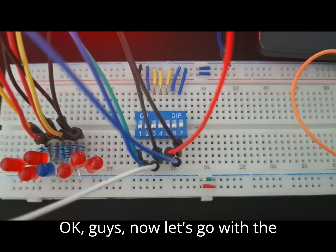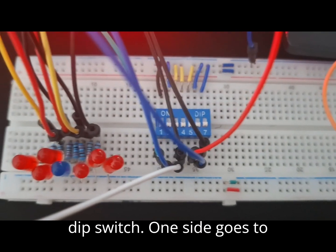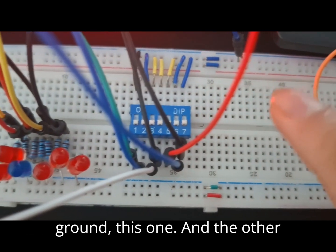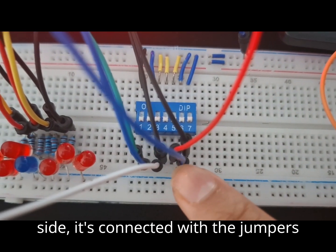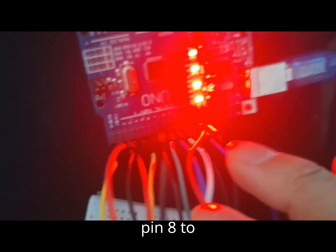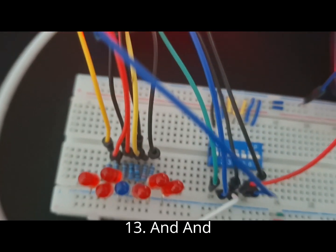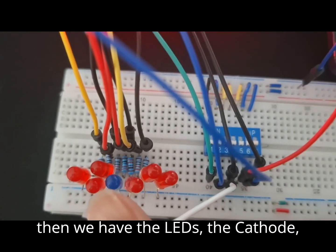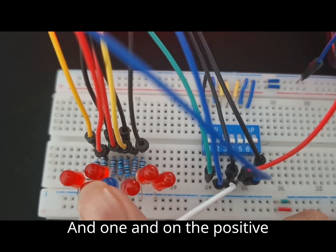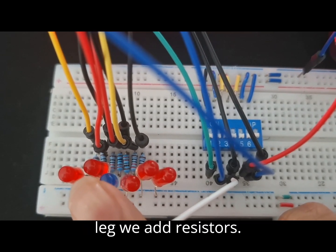Okay guys, now let's go with the physical circuit. First, we connect the DIP switch. One side goes to ground, this one, and the other side is connected with jumpers to the Arduino, from pin A to 13. And then we have the LEDs. The cathode, the negative side, goes to ground, and on the positive leg we add resistors.